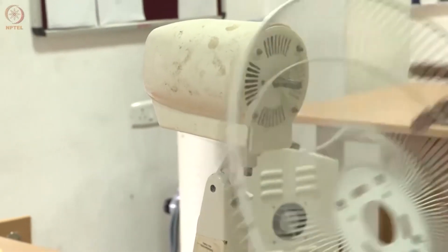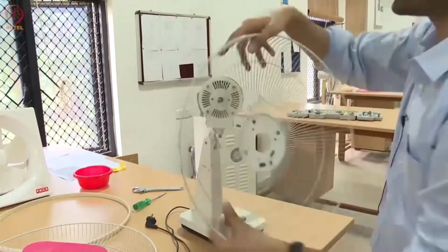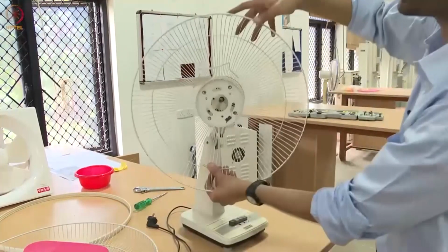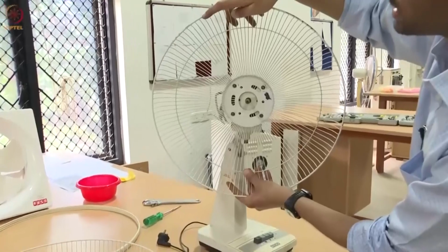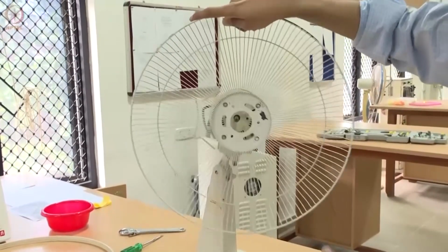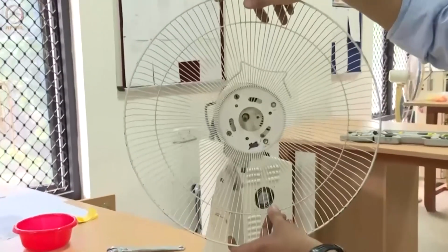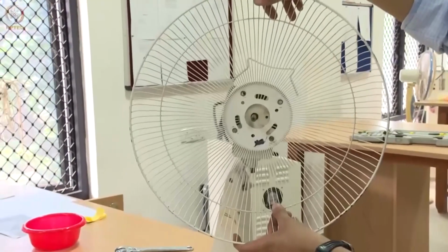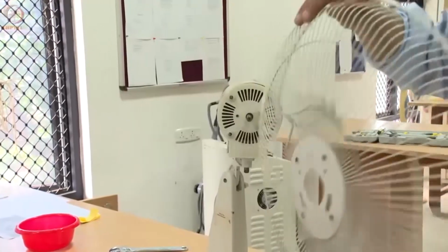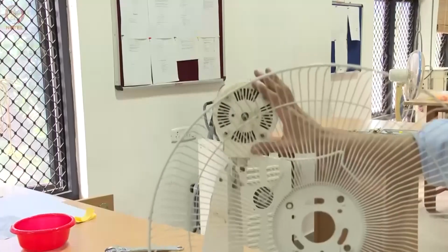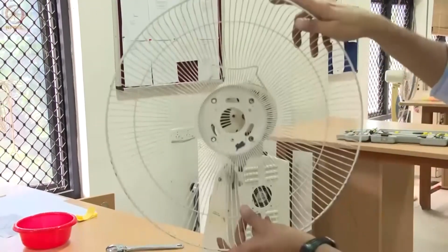Okay. So when you're putting it together, the key thing to remember is, because you have the handle at the top part, make sure it goes this way, not in an awkward position. This particular fan allows you to assemble it like this, but the latest models from this company Usha will not let you assemble it that way. So here you have to be careful. It is always a good practice to pay attention to the orientation and the alignment of different components as you dismantle them.